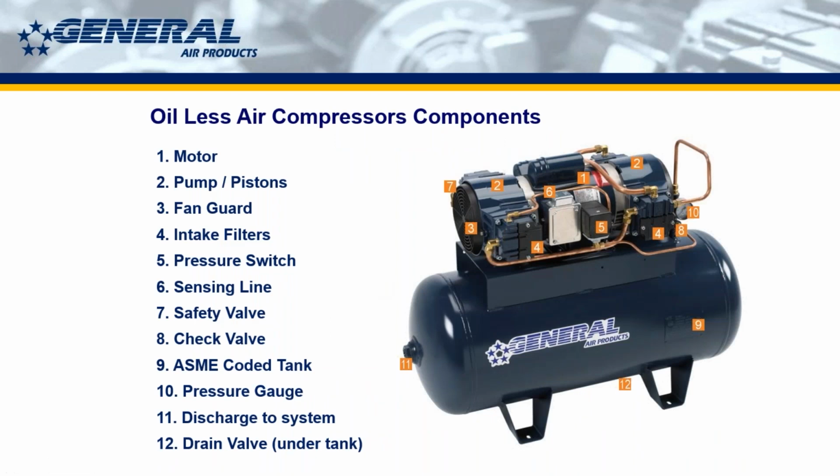Here are the major components for the oilless units. Again, you can see the motor and the pump, 1 and 2. They're stuck together, right? That's all one piece. So if the motor breaks or the pump breaks or whatever, you have to replace that whole unit. And that's just something to keep in mind. Also, number 12, you have to empty the tank of water on a regular basis.